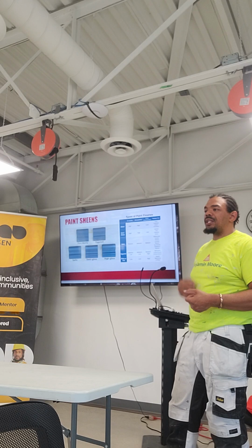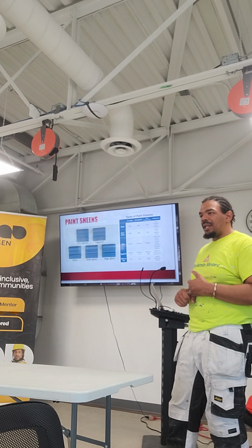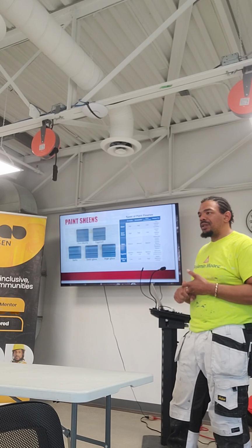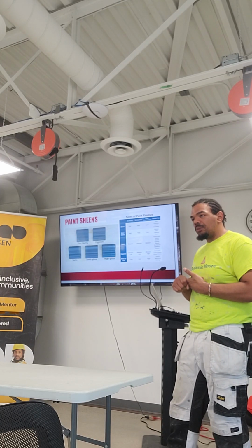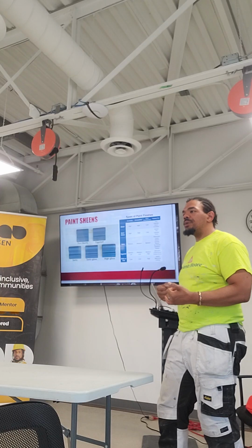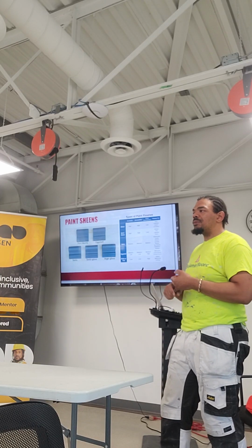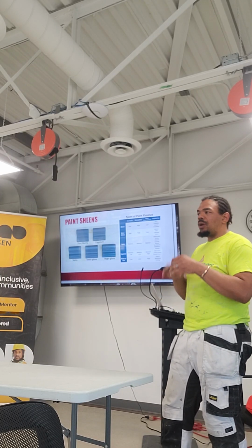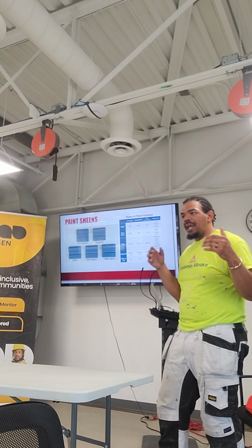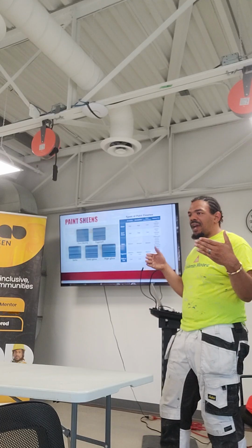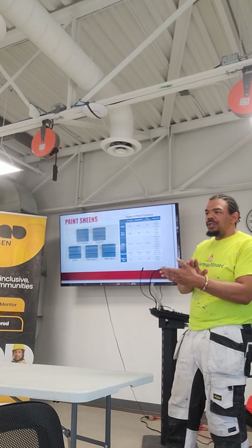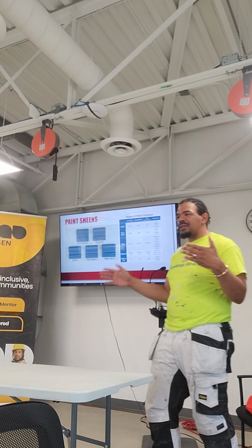So having paint that's flat, that doesn't shine a lot, means it won't show all of the imperfections on the wall, and it's washable and scrubbable, which means you get more durability for less headache in terms of doing all of the necessary prep to make a wall perfect. But you can paint it and it looks perfect because it's an optical illusion. The paint is providing you with no sheen factor, so everything blends in and looks consistent.